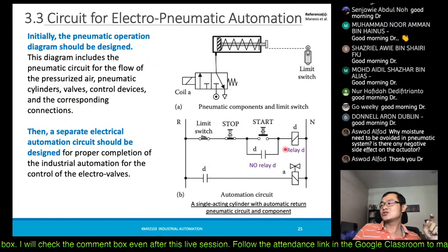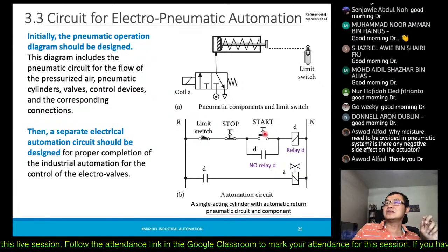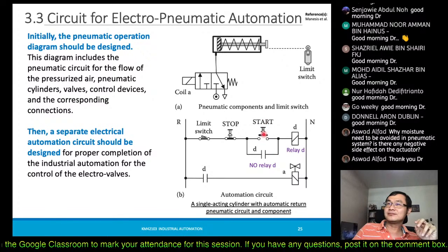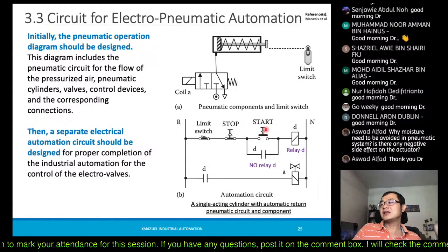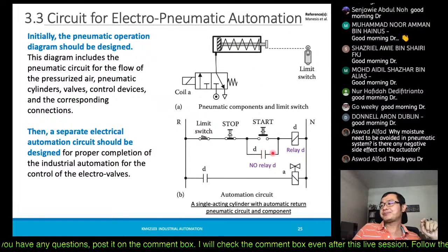It's the switching of it. So once this switches, now no matter if you release the start button or not, the operation will now start to move, because of this part.